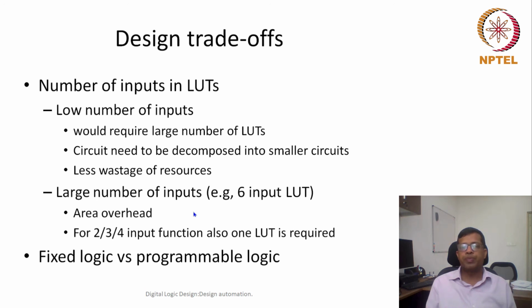On the other hand, if the number of inputs is large, for example, let's say 6 input LUT or 7 input LUTs, what would happen in that case? For any function which requires only 2 inputs or 3 inputs, most of the memory content would not be required. Many of the inputs will not be required, so that way it would be sheer wastage of hardware resources. Okay, so this is one thing.